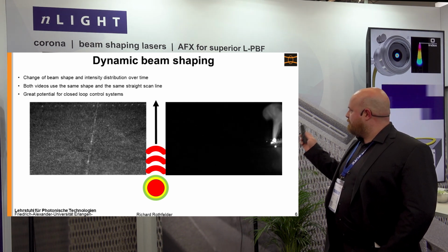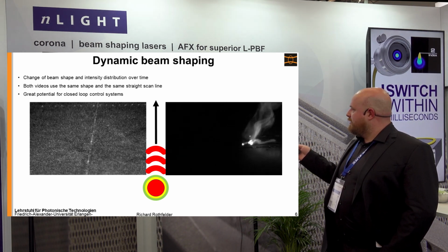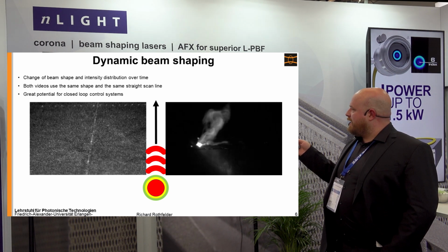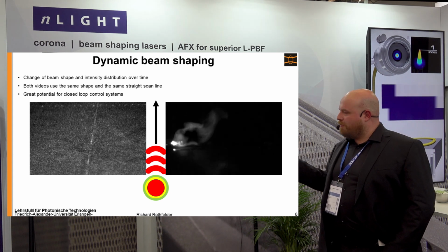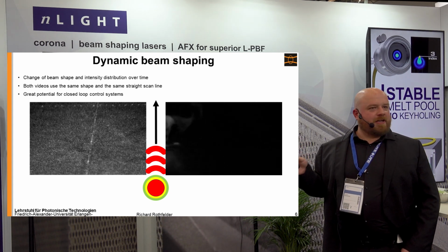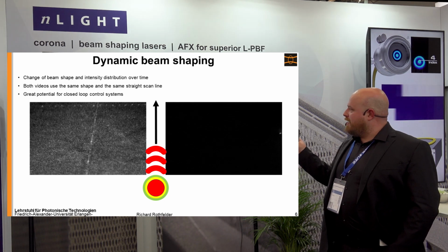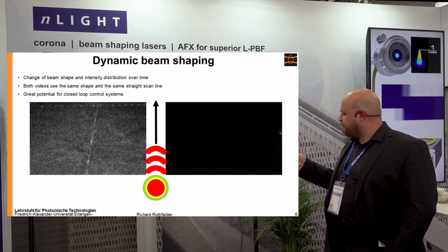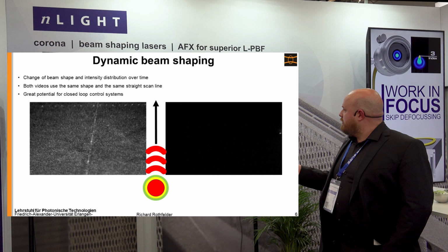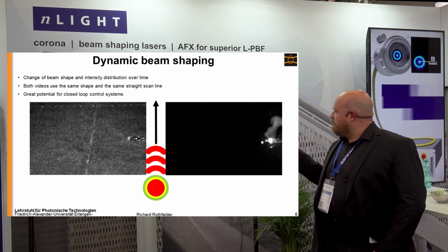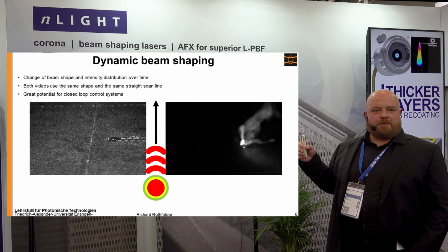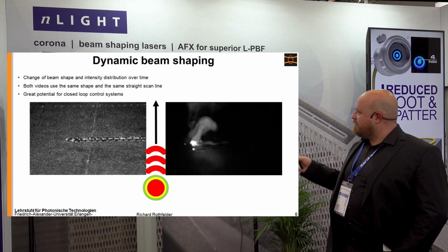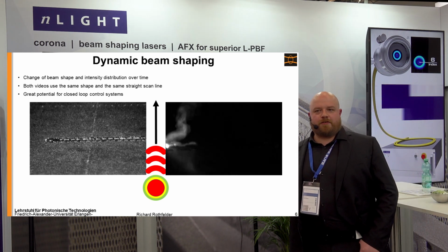And I told you it's completely the same. Just the temporal intensity distribution alters. And then we get a completely different result where we can control the flow of our melt to the millimeter. We choose the repetition time so that these curves are driven in 1 millimeter steps, and when we measure it, it is 1 millimeter to the micron. So we have an extreme degree of control via the temporal adjustment of beam shaping.